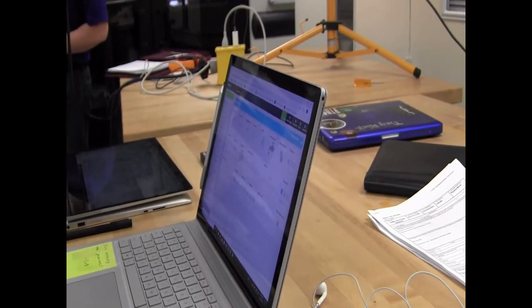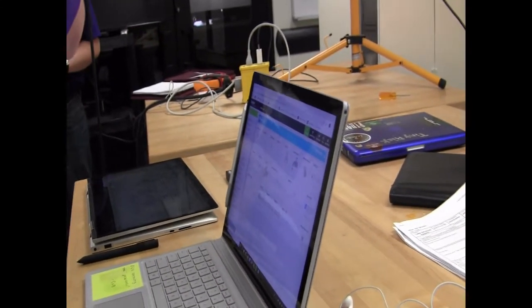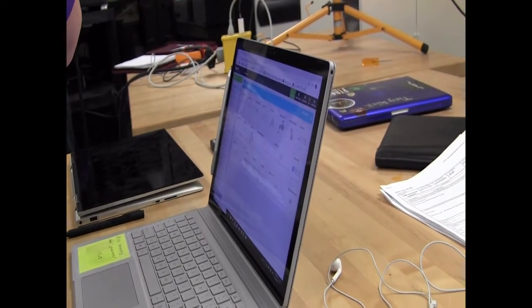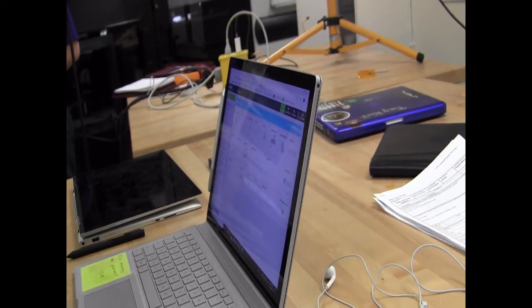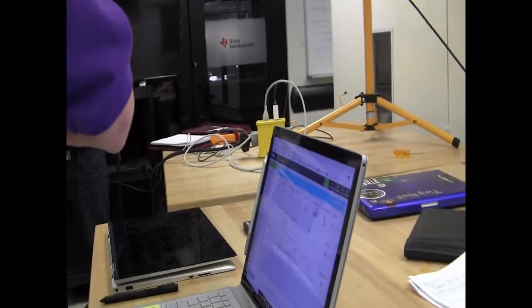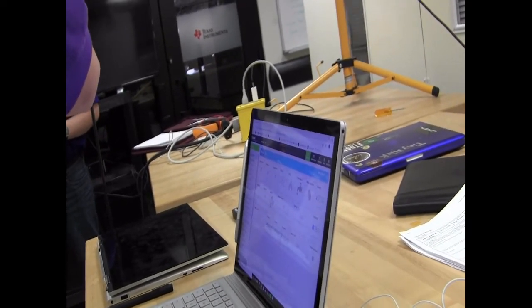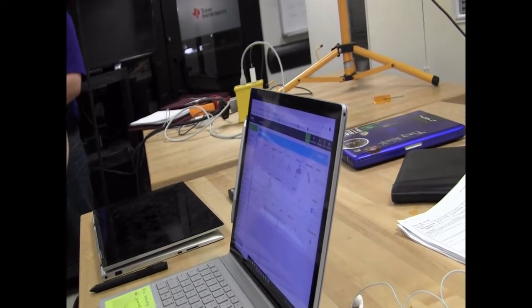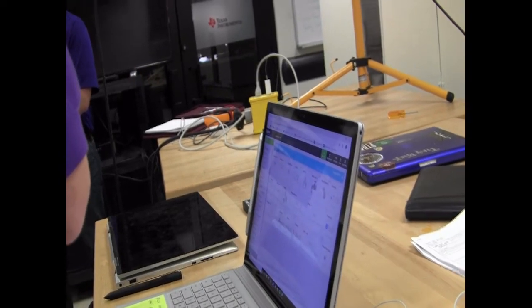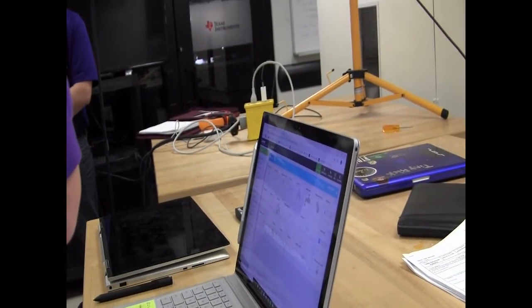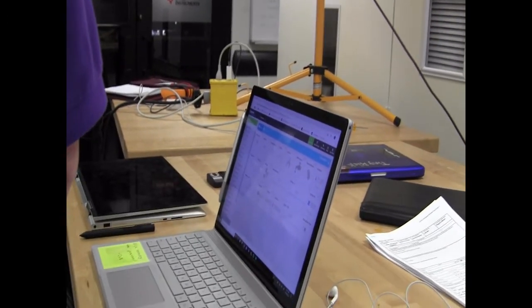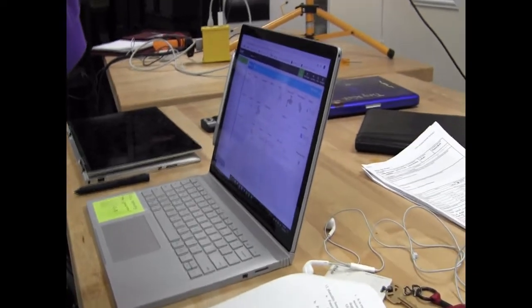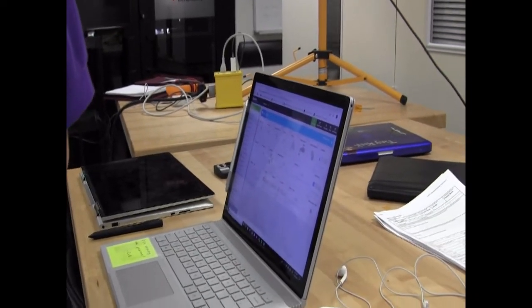But you said it measured water. So it detects submersion in water up to 1.5 inches. It measures the resistance between two prongs. The prongs are 1.5 inches long. So the sensor has that capability, but we're using it as a binary: is it wet or is it not wet? But I could mount it prongs down and be able to measure depth based on a resistance value.